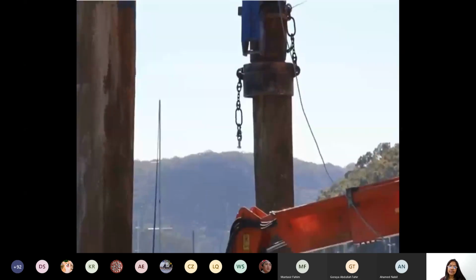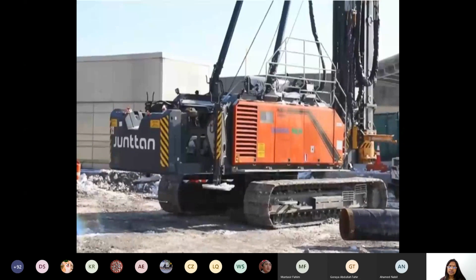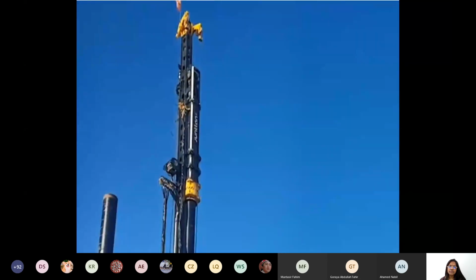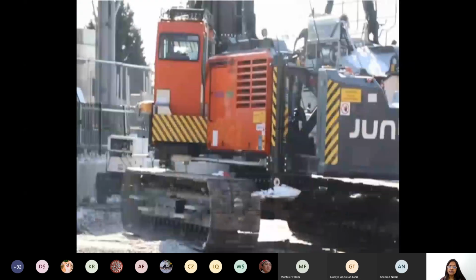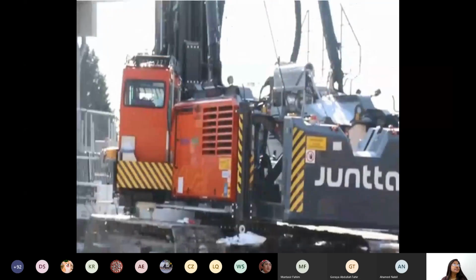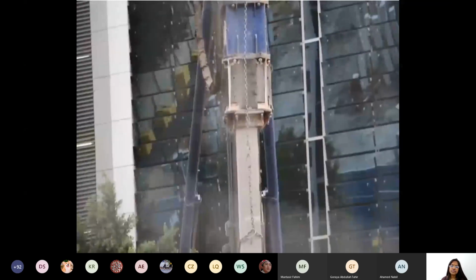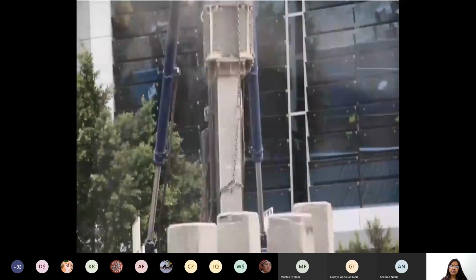The pile driving rig is a hydraulic heavy machinery that's composed of the base machine, self-erecting mast or leader, and a hammer. The machine sizes can vary from approximately 40 tons to approximately 100 tons, depending on the required leader capacity, length of the pile, and the impact hammer's weight, but also depending on the angle of the pile, as piles can be raked as well.